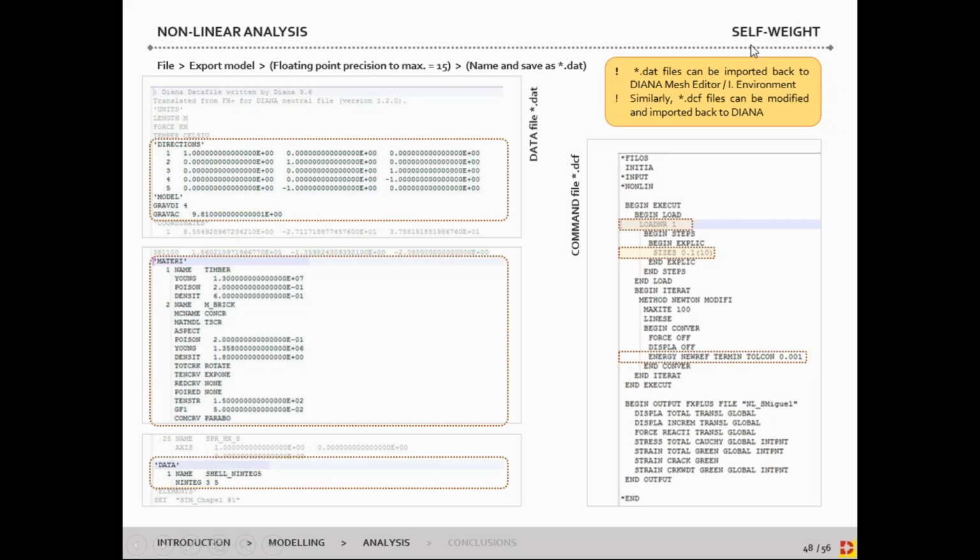If we want to check, for example, the self-weight, we would need to define in the data file all the directions that we will use later. For example, for the pushover analysis, all of the directions that we are going to implement later have to appear from moment zero of the nonlinear analysis, because we are going to concatenate one analysis to the other. So we can see here plus x, plus y, plus z, minus z, which is the gravity one, and minus y, which is one that we are going to use for the pushover.